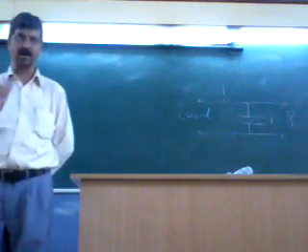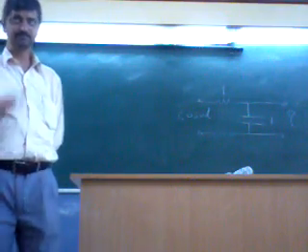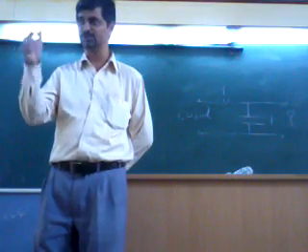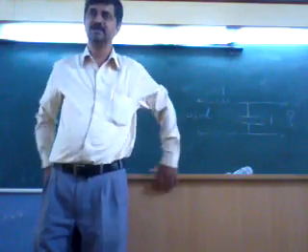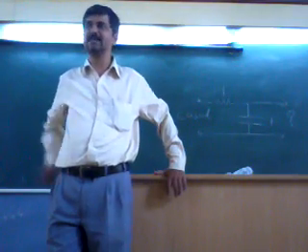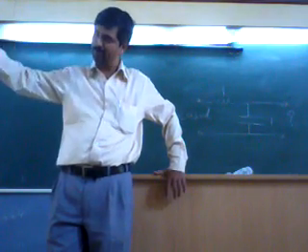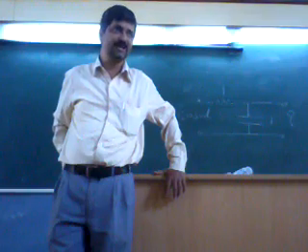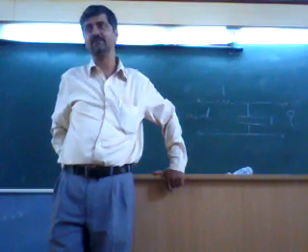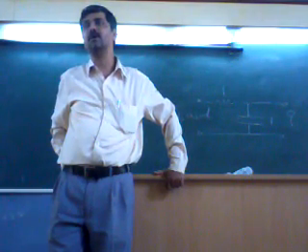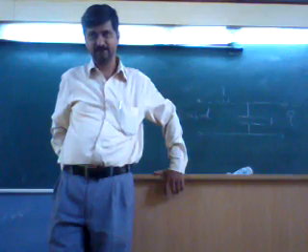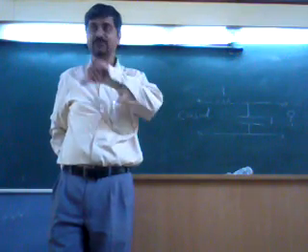If I have R, L and C in the system and I am applying a sinusoidal input of some frequency, then if I presume that it has been the situation from quite long back, it can be safely assumed that voltage and current everywhere are of the same frequency, different amplitudes and different phases.